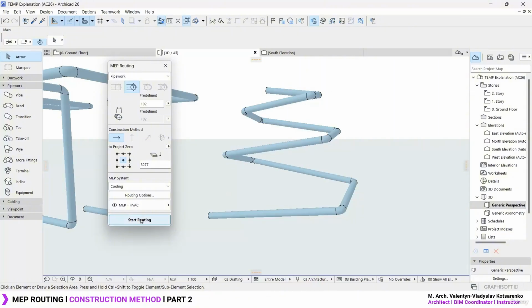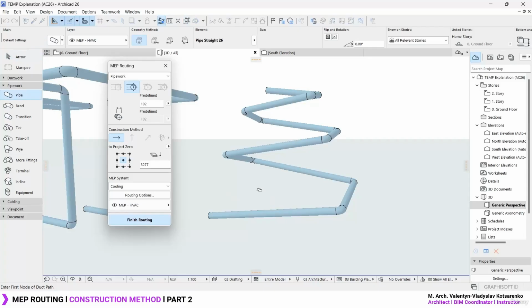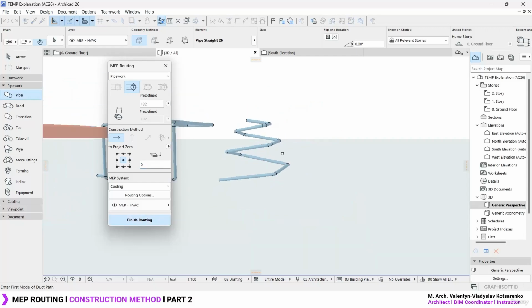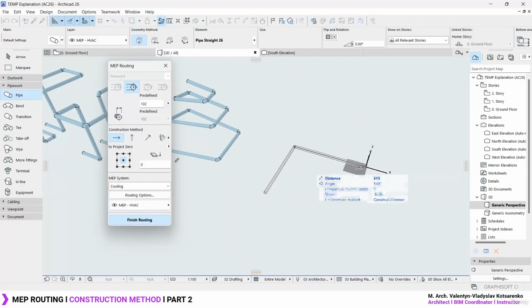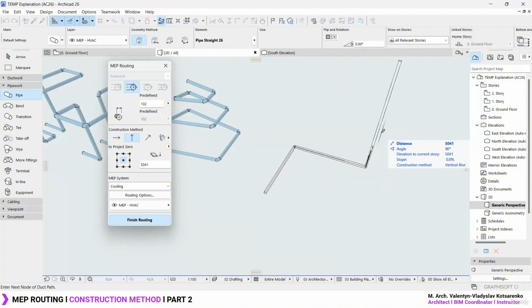So you can also create a routine in 3D. Let's say we start the routine at a vertical displacement of 0. Let's start the routine, and let's left click, and from this point you can continue horizontally, then specify the vertical displacement, but in this case it's going to be completely graphical.